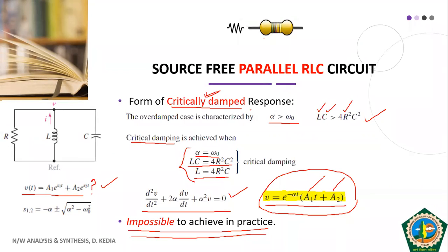So in fact, what is the reason behind that? The reason is that we cannot have the circuit component values which will give us alpha equal to omega naught, or we cannot have so much precision in the component values that your L becomes exactly equal to 4R square C. Definitely there will be some mismatch in the values that we come across related to the circuit components.